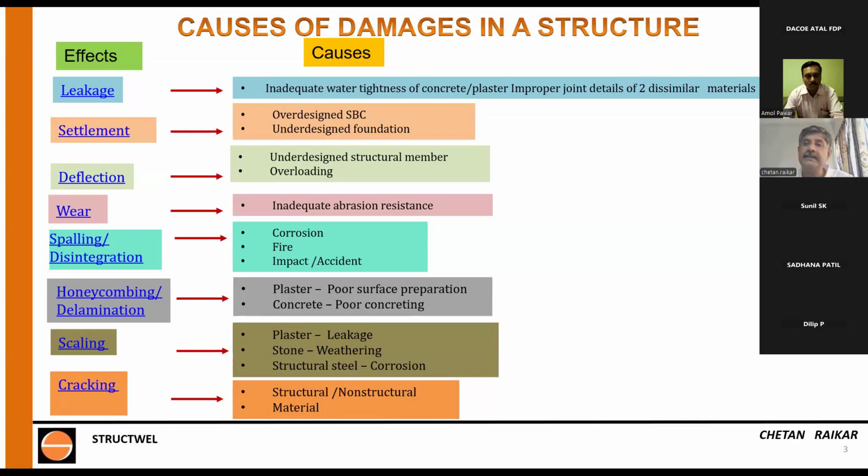The crack will form anyway, they say. And what do we do? We put a chicken mesh and we plaster over the crack, but the crack is there inside. It's just an escape route. So the joint between two dissimilar materials should not crack. Special provisions have to be taken while constructing a brickwork, and those cracks will not form.